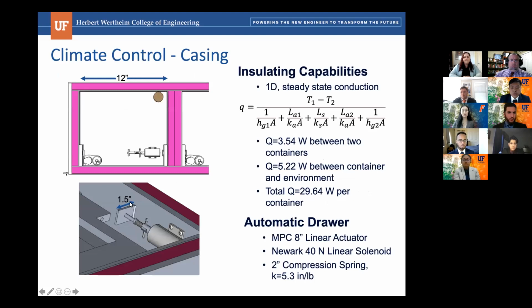The materials selected for this were a 1/8 inch aluminum sheet and a 1/2 inch plate. Aluminum was chosen for its cheaper cost compared to steel, yet it's still strong enough to hold tapped holes and actually hold the screws. It also has a higher thermal conductivity to help spread out the heat created by our thermal device around the entire thing to create a more constant temperature. We also chose a 1 inch hard styrofoam, chosen for its cheap price and its very low thermal conductivity, making it a great insulator.